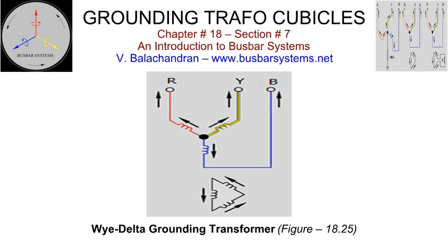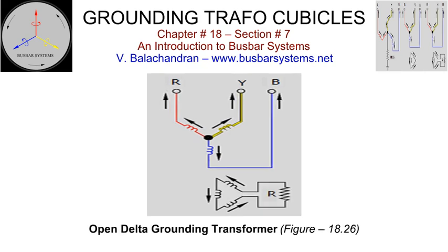The low-voltage windings are externally connected to form a closed delta connection to provide path for the zero-sequence current to flow. The sizing of the transformer can be carried out to provide the reactive volt-amperes of the capacitance to the ungrounded path. Open delta grounding transformer.